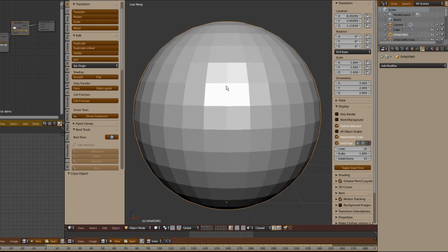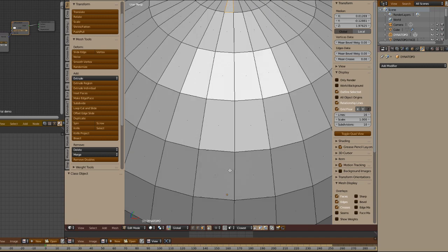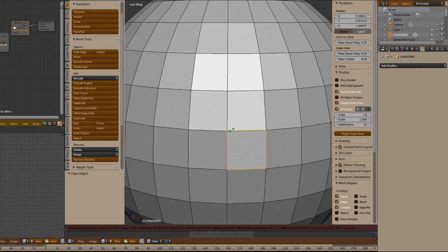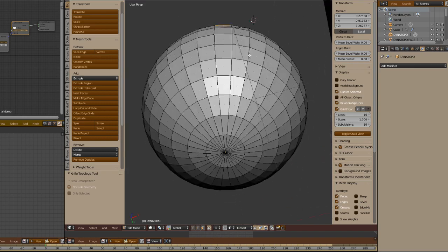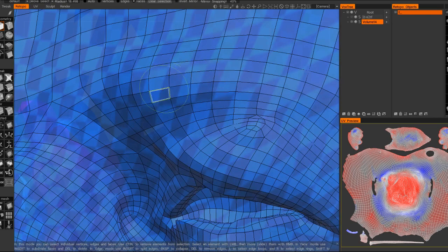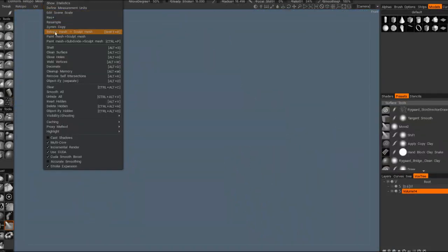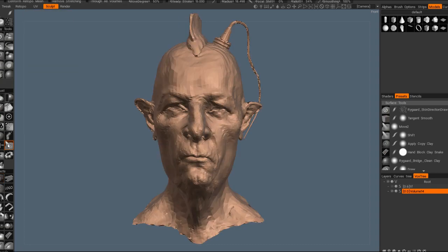As you can see, we have this sphere. This sphere is composed mostly of quads, but its top and base are made of triangles. Here I can already show a big and important differential. The user can work with quads, triangles, and n-gons, which are polygons with more than 4 edges, in the same structure of the mesh. In 3D Coat, any mesh within surface mode becomes triangular and does not allow UVs in the mesh. This means that any mesh that is brought into the sculpt room will tend toward triangles, and if the mesh has UVs, they will be lost.